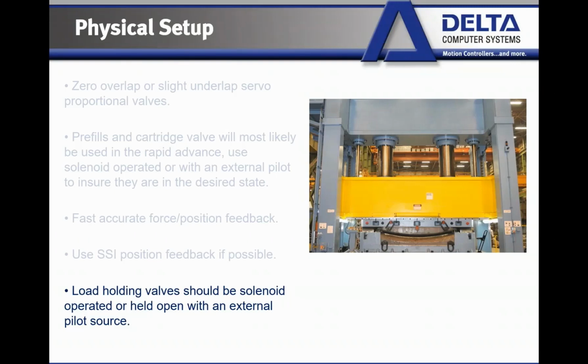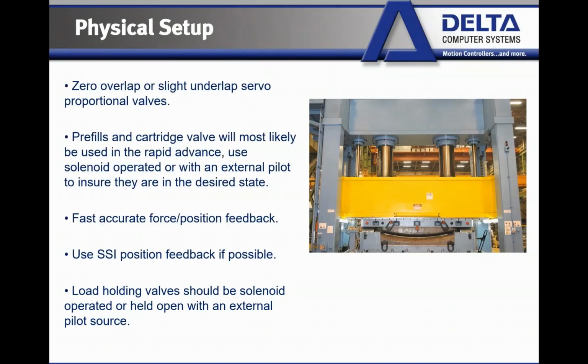Load holding valves should be solenoid operated or held open with an external pilot source. Again, this is going to make your setup much easier. It's going to just help things. It's going to reduce the time that you need, and it's going to make it so much easier when you're trying to do your commissioning, when you're trying to set things up. So just a brief view on the physical setup.